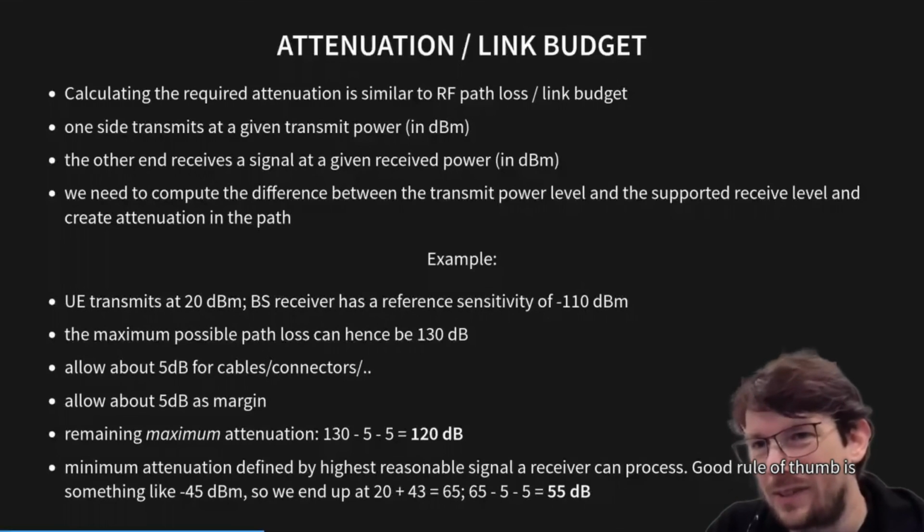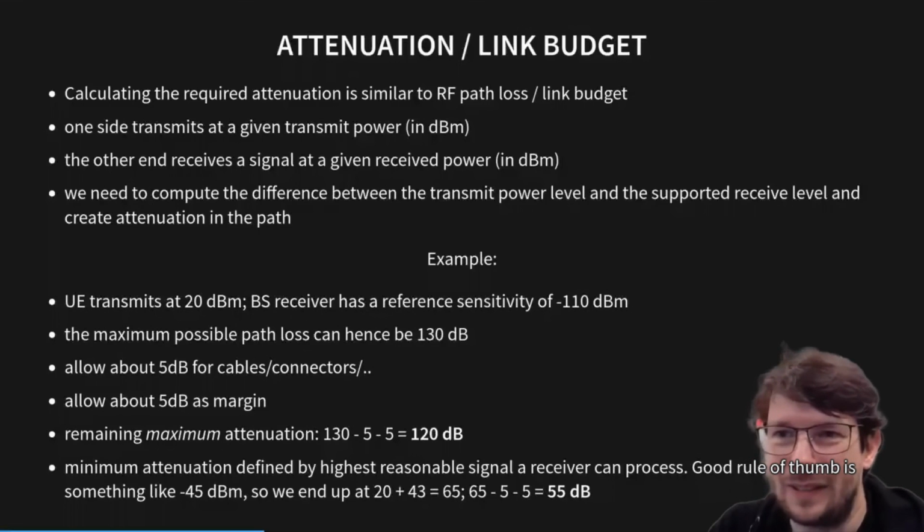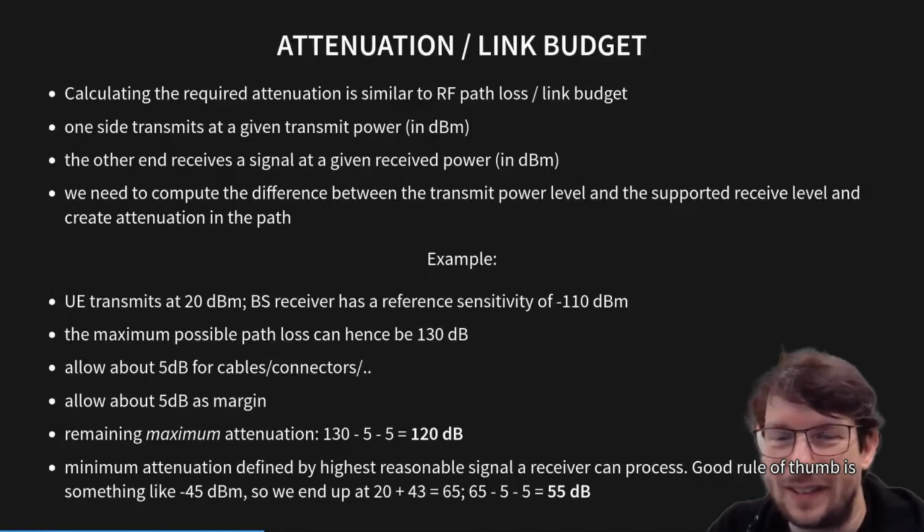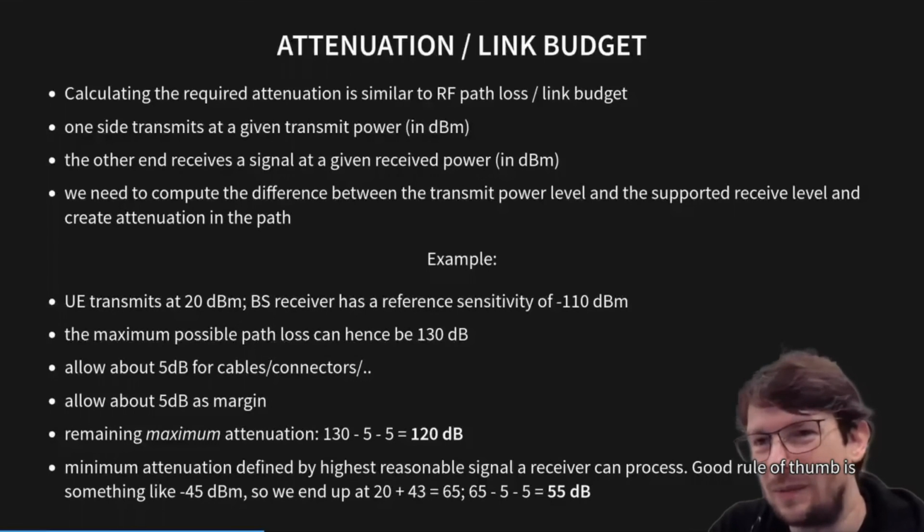That would be an ultra strong receive signal that happens if your phone is in a commercial GSM network, if your phone is located very close to the base station antenna. So that's something that can happen in reality. And at any base station, at least. I'm not sure about SDR equipment, but I would expect the same. But at least a commercial base station should be able to deal with that kind of signal level. So if we look at that and we look at the equation that way, then it means we have a transmitter at plus 20 dBm.